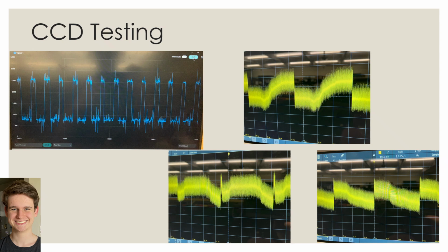Software testing at this point has reached completion for CCD data acquisition, as showcased here with the voltage output of the CCD being displayed on the oscilloscope and the ADC's converted integer values displayed with the serial plotter function in Arduino's IDE. These results come from a finger being placed at various points along the sensor, which is visible in an upward spike of each frame, which indicates a darker lighting on that area of the sensor. The sensor's output is controlled by timed voltage signals from the microcontroller, just as it will be in the final project design, with testing using the ESP32 dev board instead of the embedded MCU on the PCB.